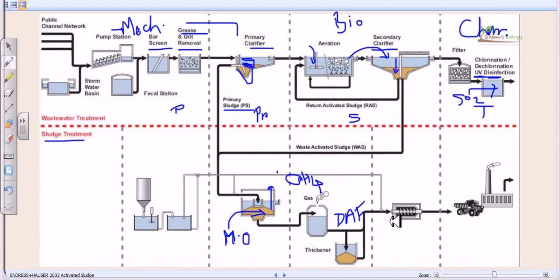So we dry them, we dewater them utilizing chambers; these chambers are called centrifuges. And we know in scientific labs we have used centrifuges, and those centrifuges are small, micro centrifuges. But the centrifuges used in sludge dewatering are really huge, mega centrifuges. In this centrifuge the mechanism remains the same: the water is placed at the top, and the sludge is sedimented at the bottom. So it's a layer of sludge at the bottom.